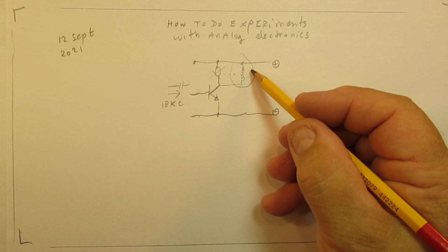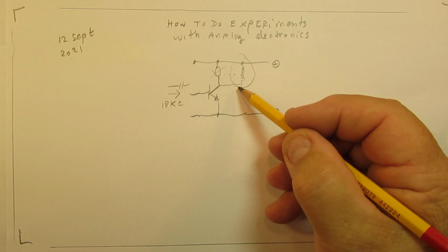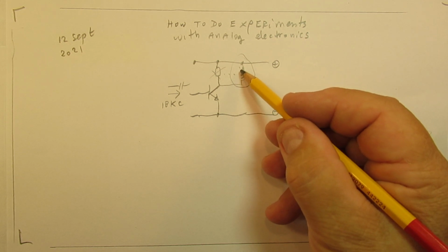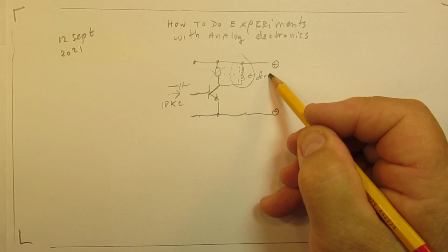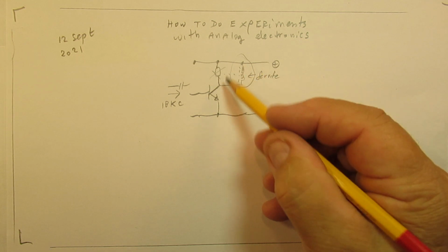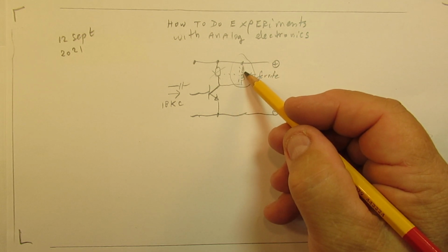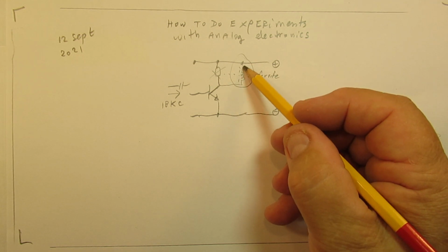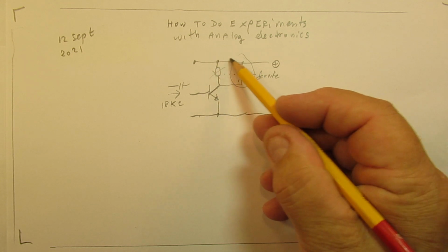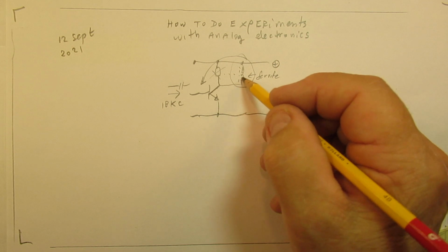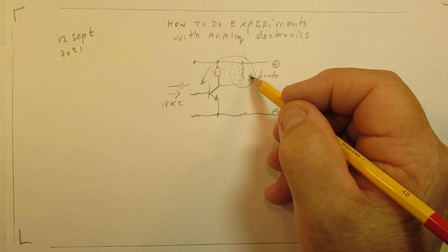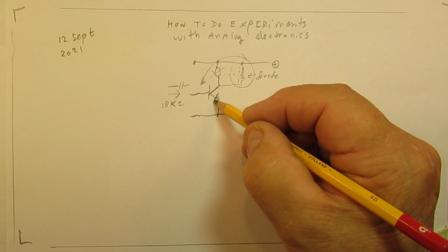But when the magnetic field inside of that core, say it's ferrite, often ferrite, collapses, there is a voltage pulse sent back to the transistor circuit, and that could be so high that the transistor is damaged.